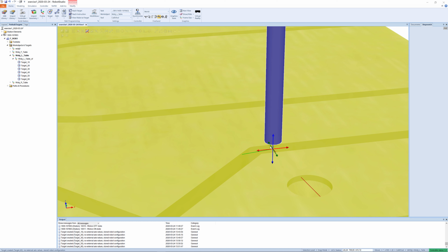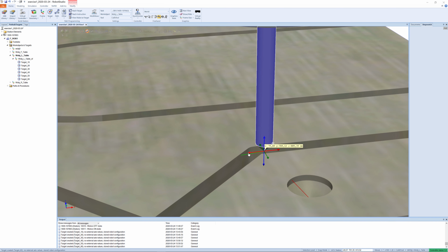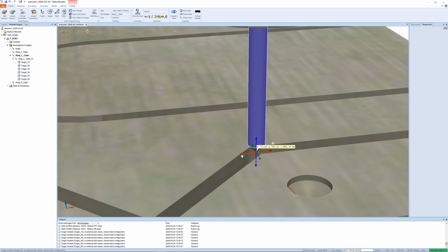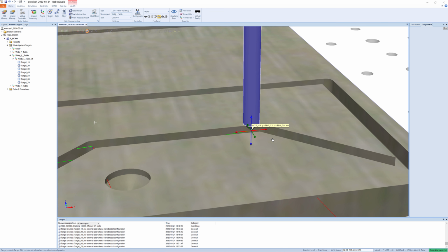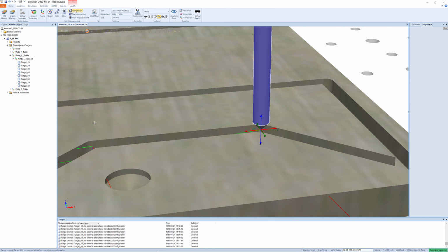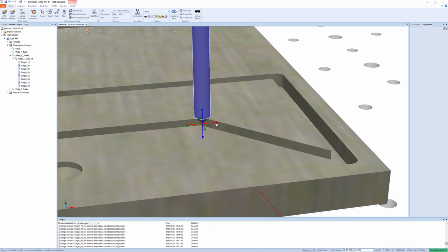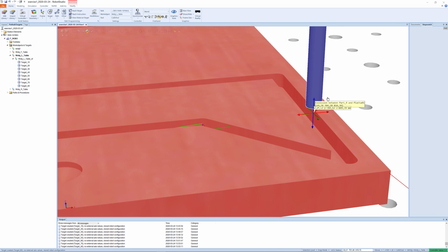I go up a little bit. Okay, here we don't have a near miss. Move in the other direction until we get the near miss again, like that. So this should be pretty okay. Teach target. And then continue in this way forward till here, teach target. And then until we go into this slot.